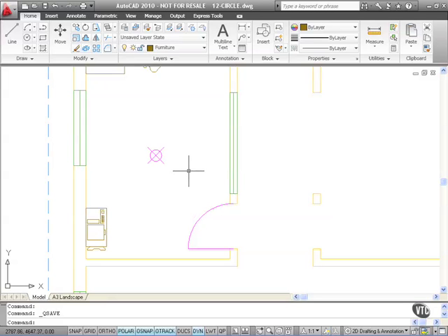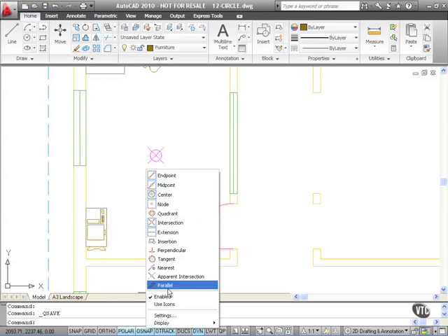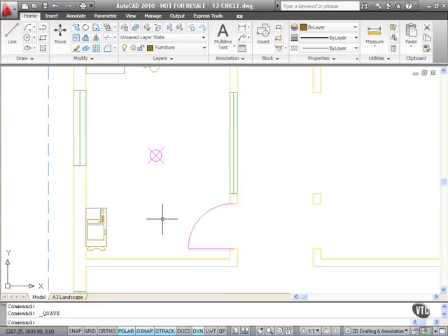I'm going to show you two different types of circles. There are also many other types of circles in AutoCAD. Before we do anything though, we go down to OSnap on the status bar, right click, and we make sure that the node snap is on, because when we use our points, remember, it's a node snap. So node is on, it's got the blue square around it. So hit escape to lose the menu. Remember not to click on node because that will switch that snap off.